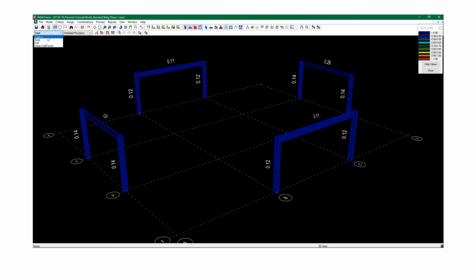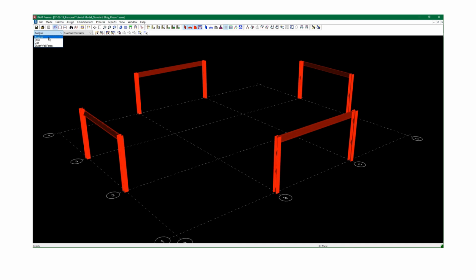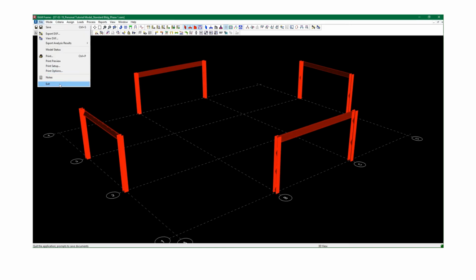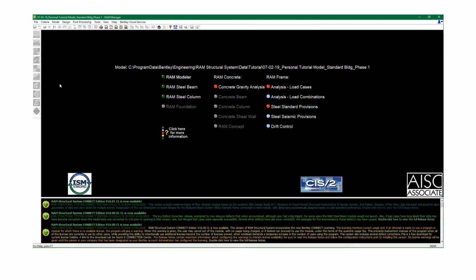Now, again, like I said, I will make sure that we're doing everything right. This is about the proper settings just as well. So I know that there were some placeholders that were incorporated earlier for my seismic load case. So I will go ahead and update those placeholders. However, before I do that, I am going to take a second to go into the calculation of the self weight that would actually be tributary to the diaphragm.